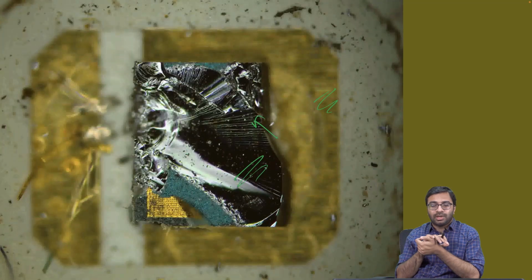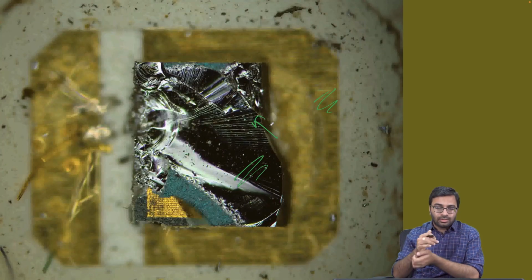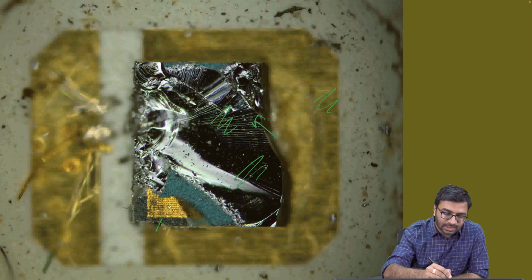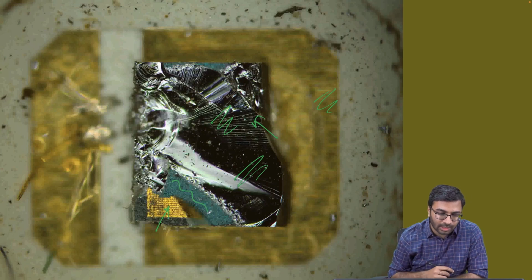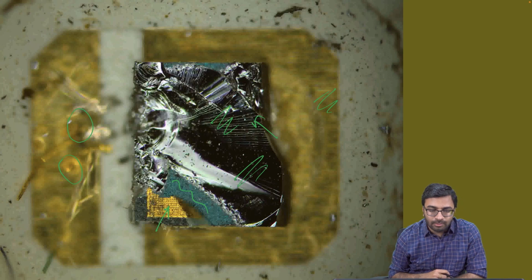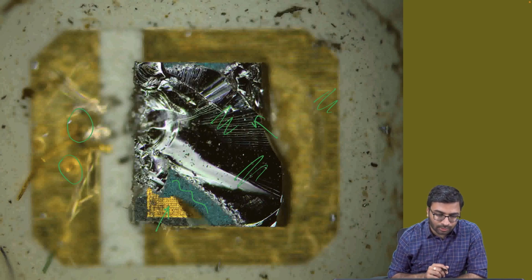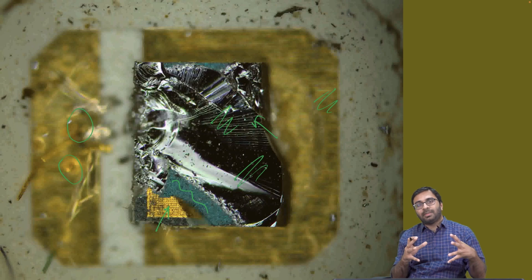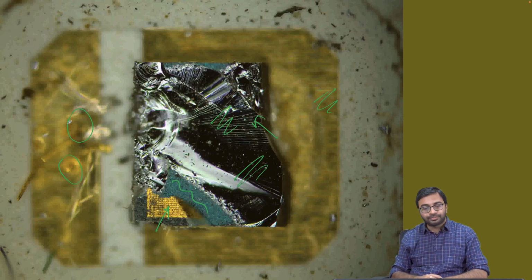So just to provide you that information. So this is the electrode at the back side, this is the top electrode, then in the middle you have another material. This is where you connect your metal wire electrodes. So this is the structure of a capacitive humidity sensor.